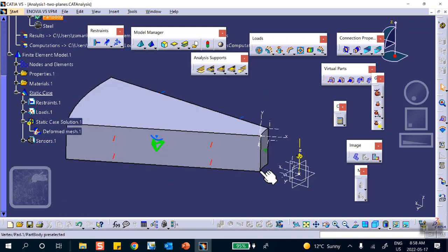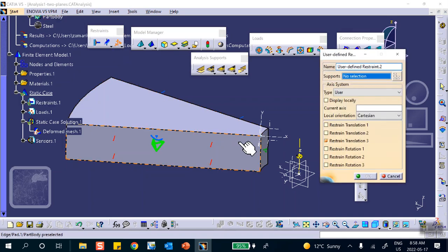So we take 1 point and say, hey, you can go up or down. So that is user-defined restraint right there, user-defined. 1 point. Now just be careful, because remember I used the user coordinate system. Still user is showing. You may get lucky, but sometimes if you're not careful, up and down of the global coordinate system is different from up and down of the local coordinate system.